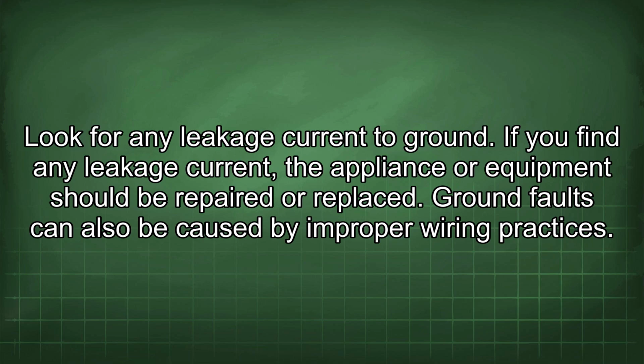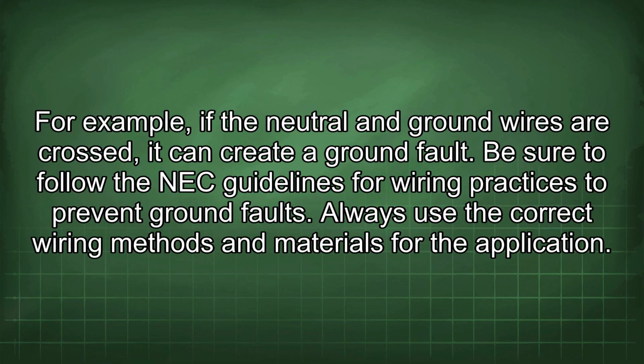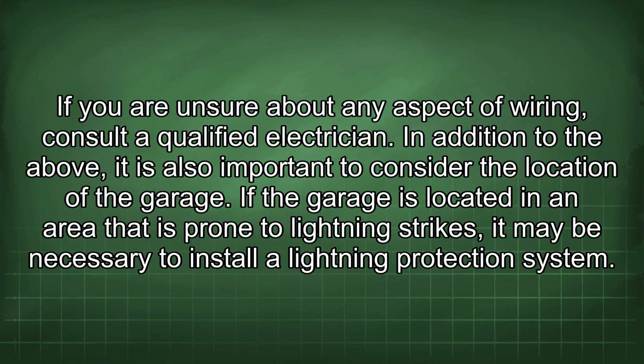Ground faults can also be caused by improper wiring practices. For example, if the neutral and ground wires are crossed, it can create a ground fault. Be sure to follow the NEC guidelines for wiring practices to prevent ground faults. Always use the correct wiring methods and materials for the application. If you are unsure about any aspect of wiring, consult a qualified electrician.